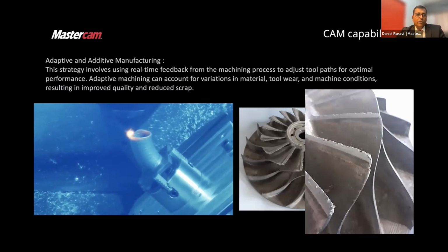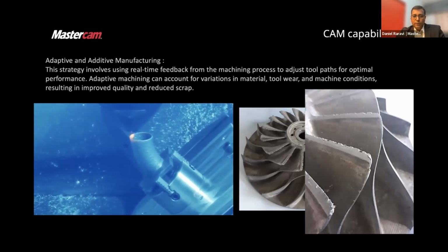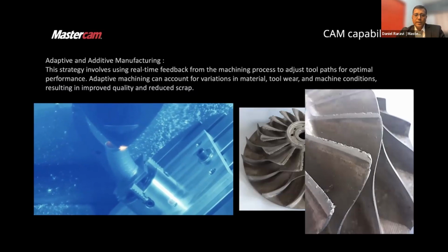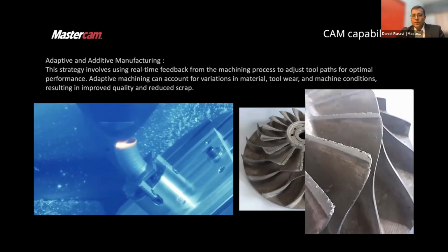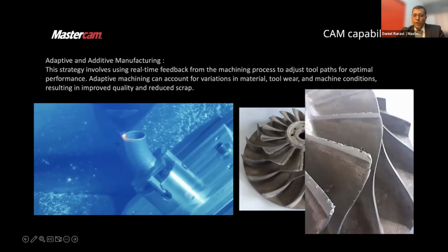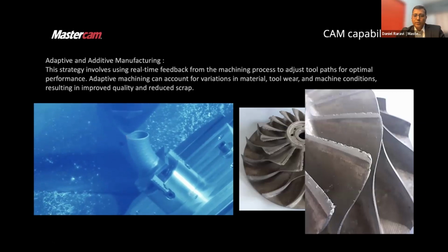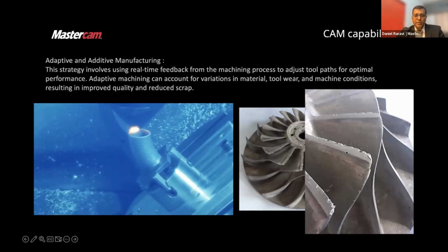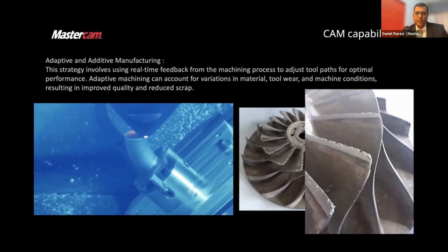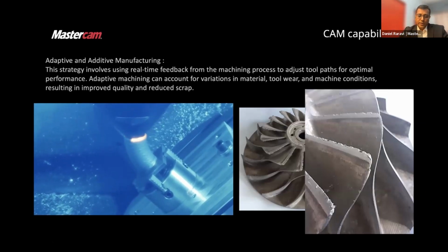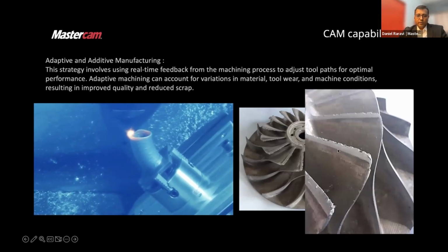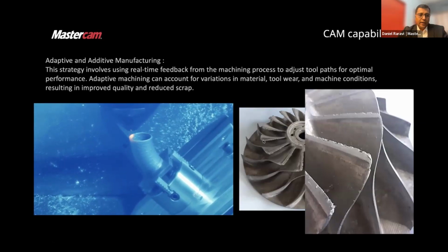appreciable. And therefore, adaptive manufacturing makes use of advanced CAM systems, both CAD and CAM systems, using also vision-based and laser-based metrology systems to identify where the damaged edges are, and then locally repair it so that you're depositing material only in the areas which are damaged, and then using a combination of hybrid manufacturing, which is using additive and subtractive manufacturing to then machine those areas specifically to blend with the geometry of the overall CAD model.